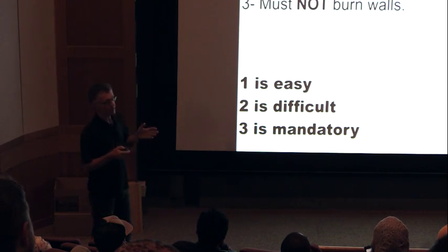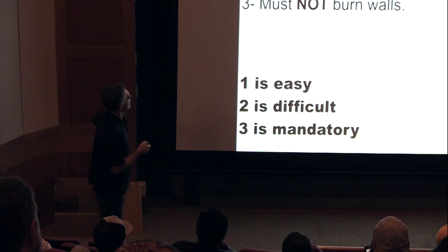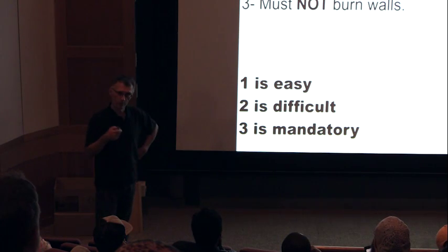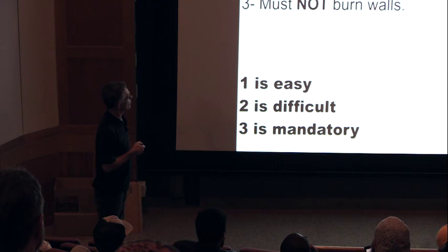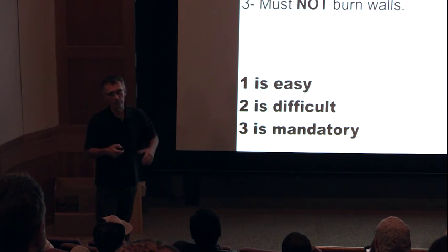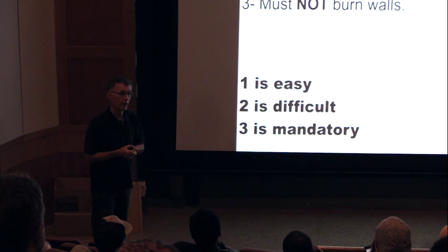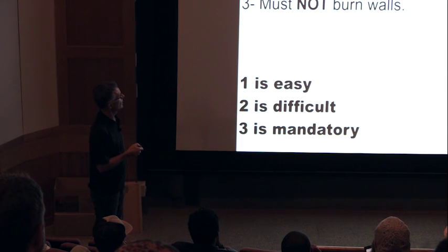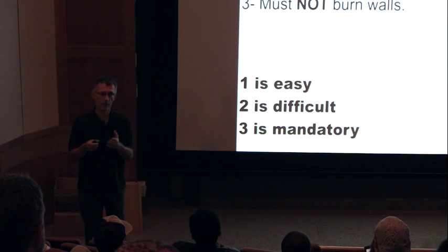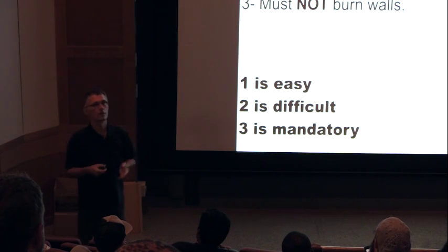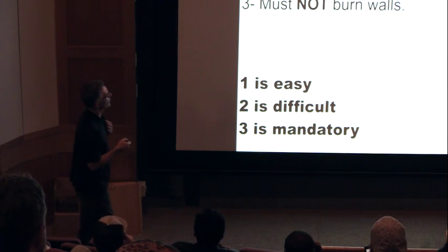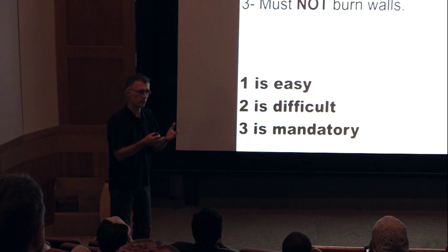Except that if the compressor is able to give you a higher pressure, what should not happen is that the combustion chamber must not do something stupid like making more pollutants. And that's easy to have this problem, because if the pressure goes up at the inlet of the chamber, the temperature goes up, so the NOx is going to go up. So our role here is not, we are not leading this thing, we just should not stop it.